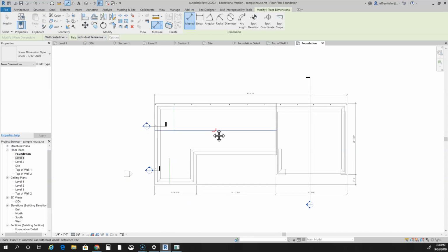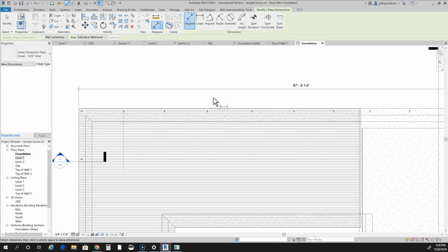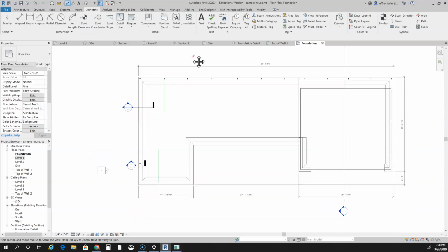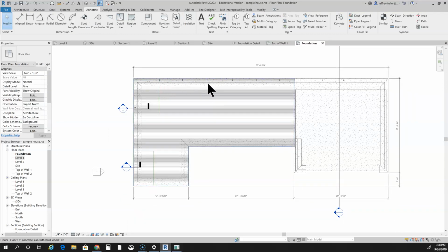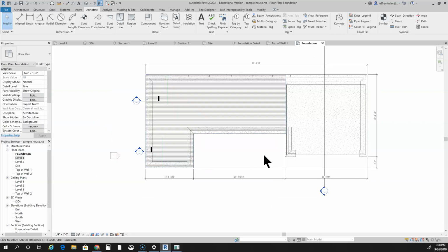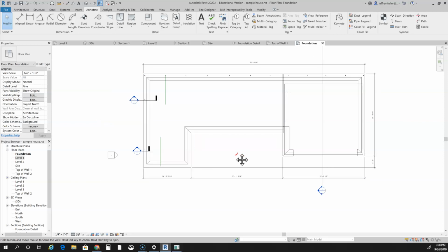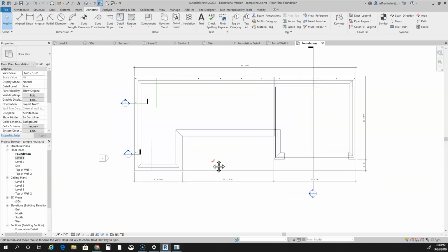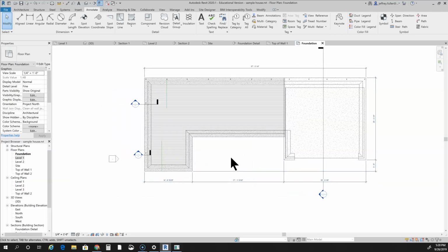That's your top view, and you can see that your J-bolts are all located here, and we shouldn't really need to annotate those from here. We just want to show that they're there. And so we've already got our rebar annotated from the detail view, and that should be all we need to do. In this view, it's just the dimensions. Okay.